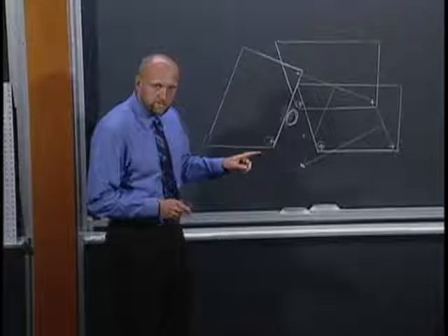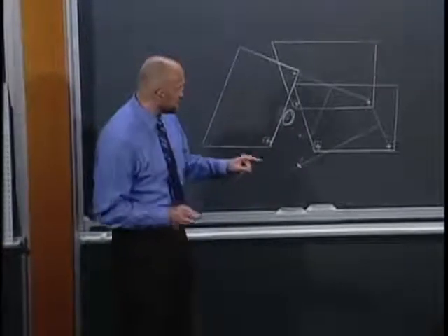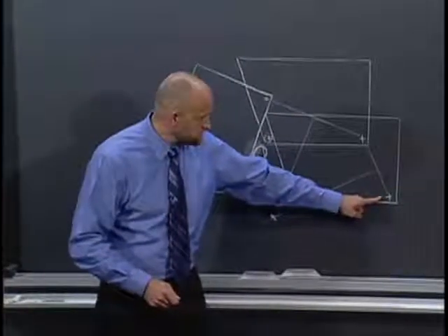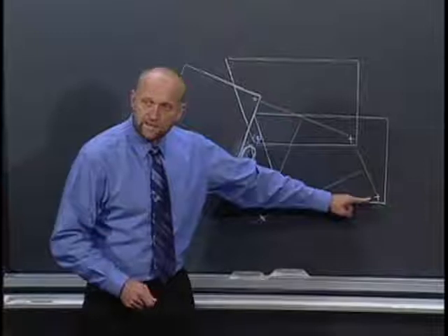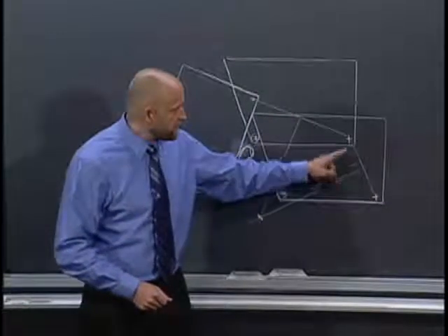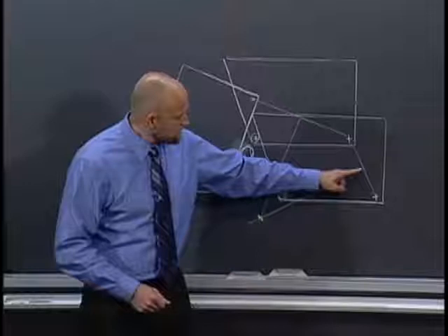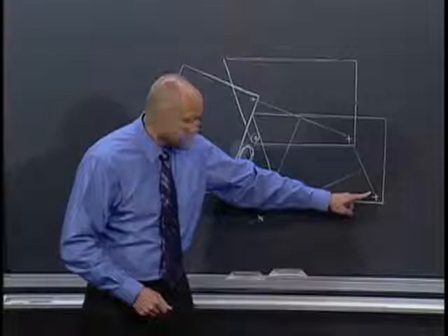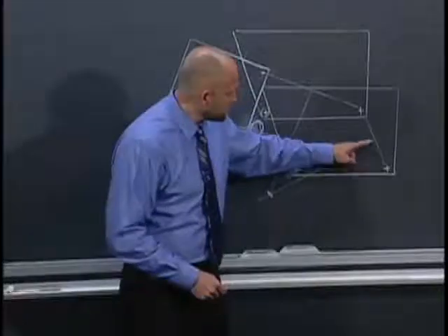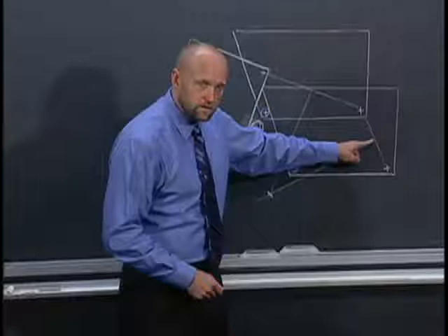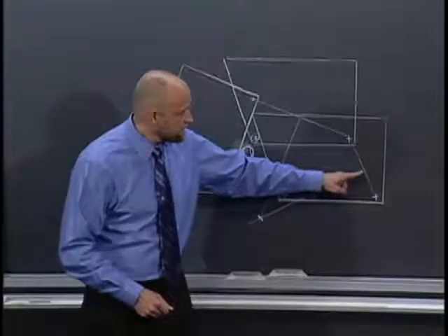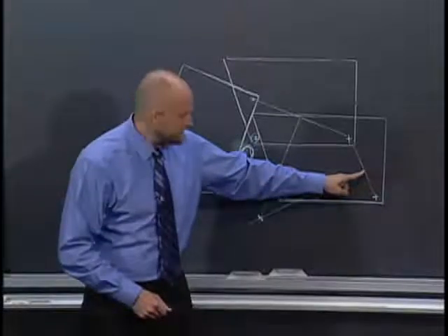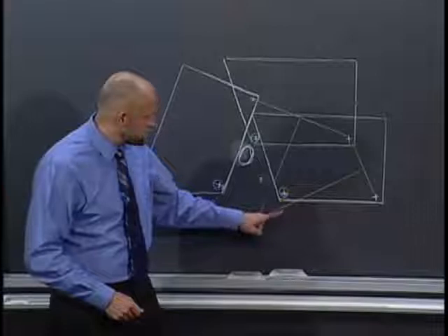Now, there are multiple ways to do this, but I'm going to sketch out one relatively easy way. I took 2 of the points on the right side of the mechanism, and I connected them with a line segment. Then I found the middle of that line segment. So this segment of the line above it is the same length as this segment of the line below it. Then I constructed with a square piece of paper another line that's perpendicular and goes through the midpoint of that segment, and that extends out in this direction.